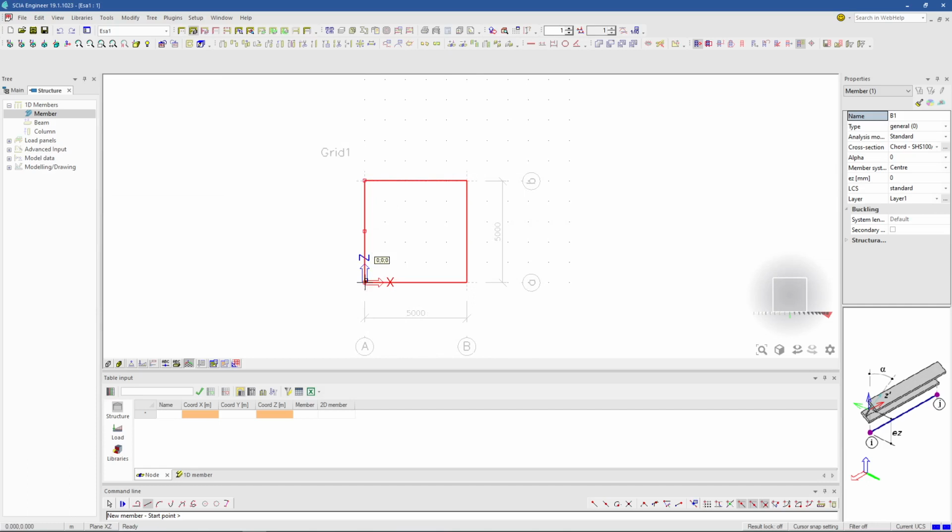Putting a cross brace, we've introduced a cross brace. Now, this is analogous to what we see in portal frames or in warehouse design. You see those braces assist in resisting lateral deformations. So this is the essence of a truss.